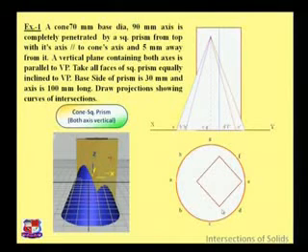All faces or sides of this square make an angle of 45 degrees with the XY line. So if I draw a line over here, then this angle would be 45 degrees. After drawing, this is a square of given side length. What is the side length of this given square? 30 mm. Draw this square of 30 mm sides. This offset distance is 5 mm. It is given in the data.